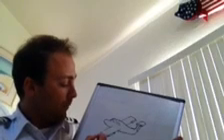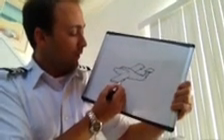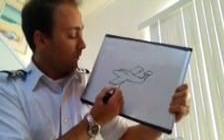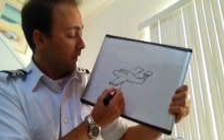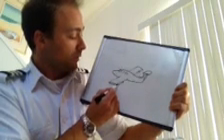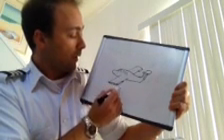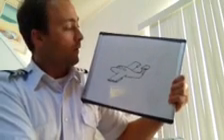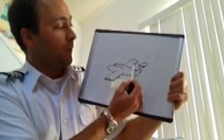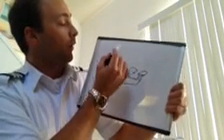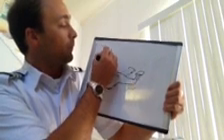The way it works, we have an example, an airplane being banked to the left. The left aileron has been raised into the relative wind, and we can see a decrease in the camber and also a decrease in the angle of attack, as opposed to if the aileron was neutral. And on the aileron that's dropped, lowered into the relative wind.